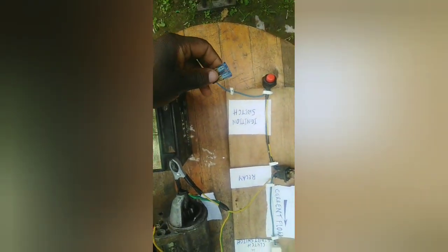Your fuse may be blown, your relay may have blown, your switch may be faulty, there might be a fault in your starter motor, maybe your solenoid is bad, maybe your brushes are worn, maybe there is an open wire in your field windings, maybe your armature.